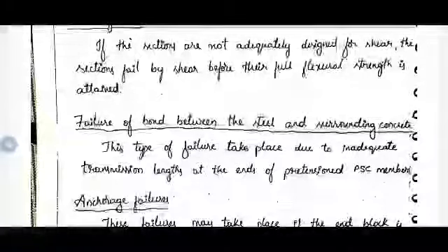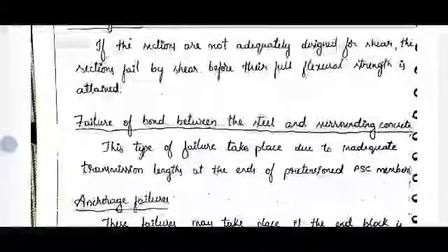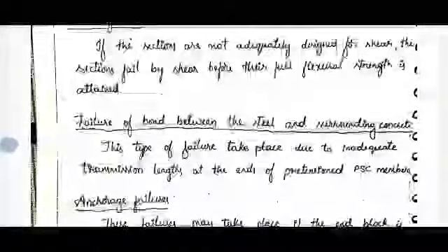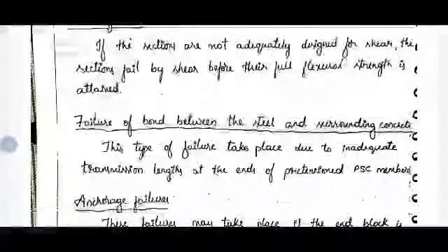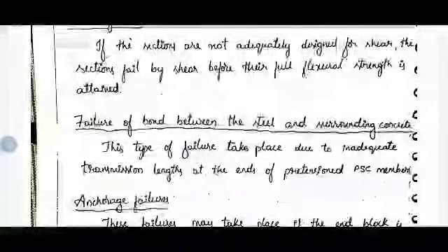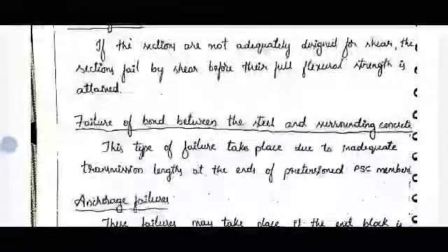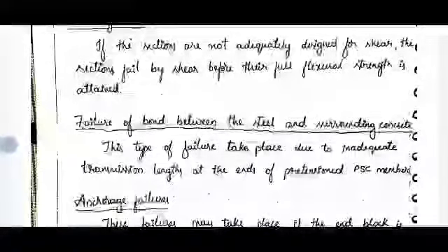So in this failure, in the first module itself we discussed that high strength concrete and high strength steel are required in PSC. Especially in the case of post-tensioning, there will not be bonding at all between tendons and concrete, because after casting we are going to provide tendons. So to provide bonding, we are going to provide grouting. So the strength of grouting will play a major role in the bond between concrete and grout, as well as grout and tendon. There are two bondings and both should be proper. If the bonding is not proper, then the strength of the tendons in the tensile zone will go on decreasing and there may be chances of failure.